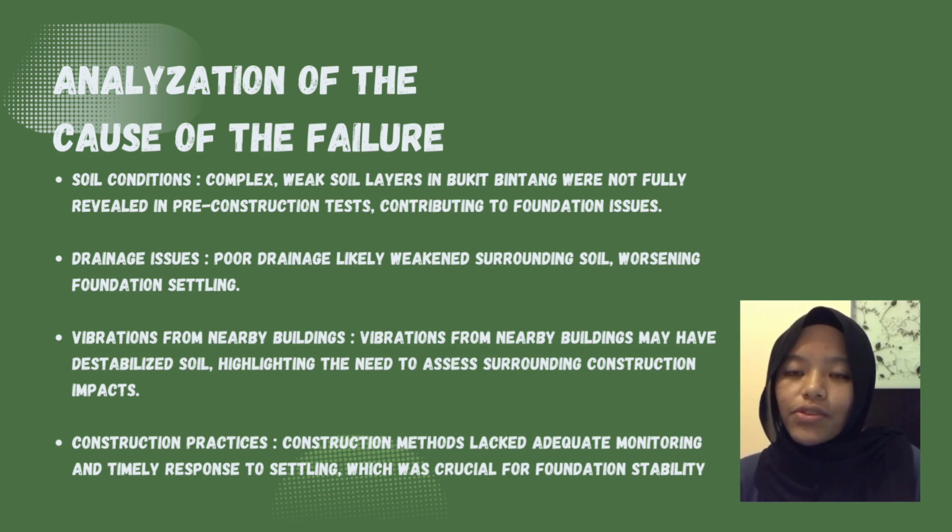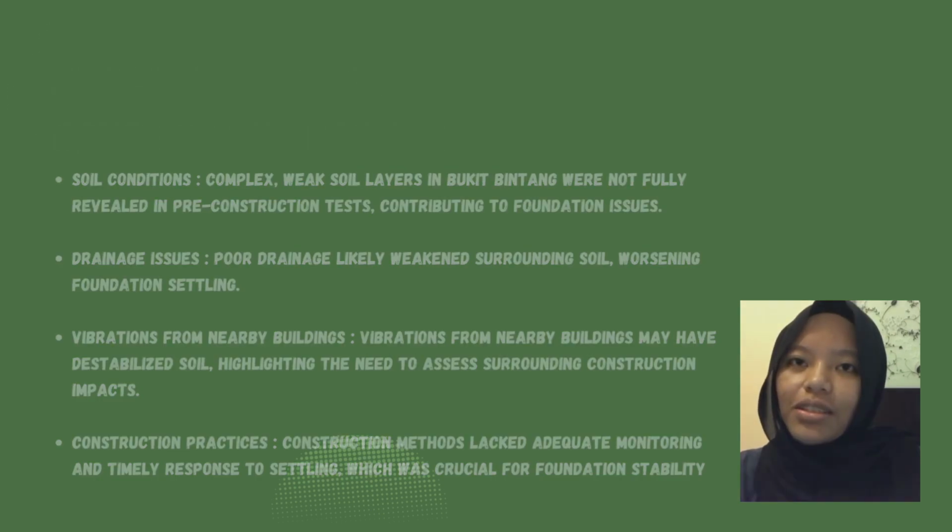Number four, construction practice. The construction method lacked adequate monitoring and timely response to the settling, which was crucial in maintaining foundation stability. So, in summary, the failure was caused by a combination of factors such as inadequate soil assessment, poor drainage condition, and the vibration impact from nearby construction.